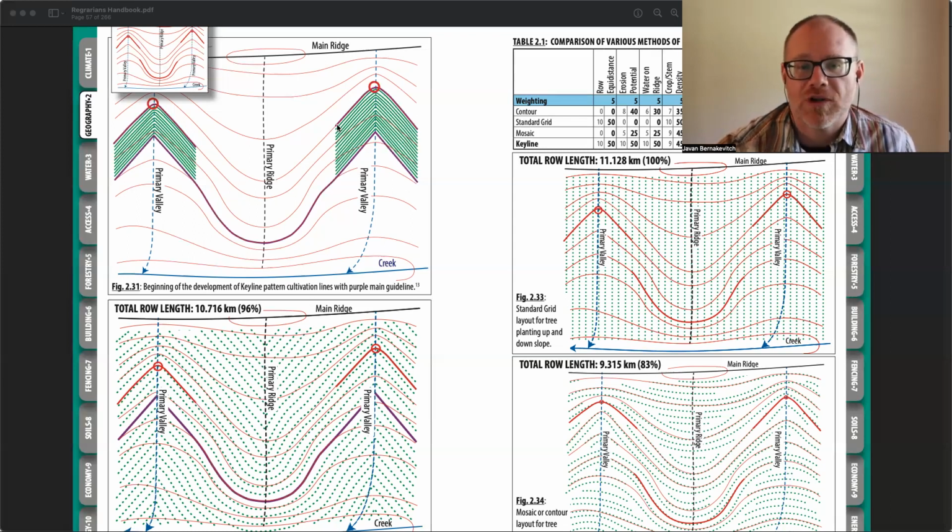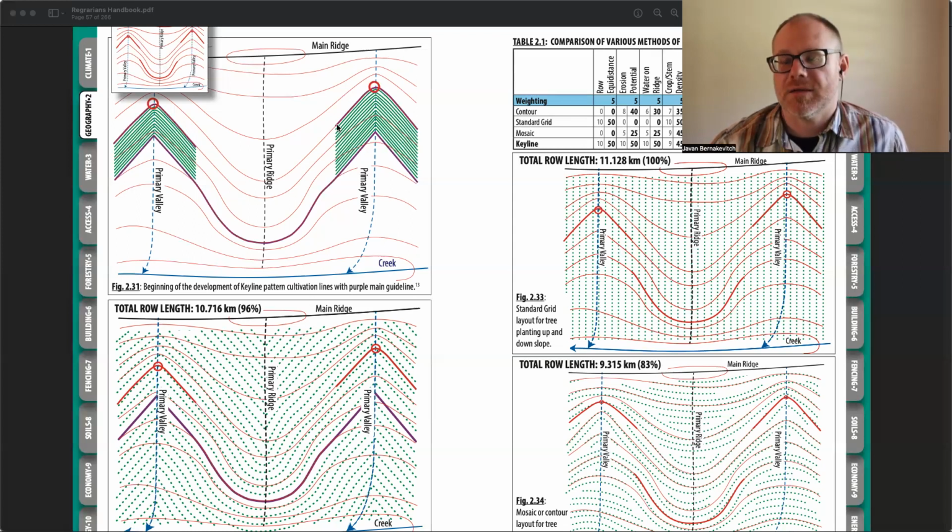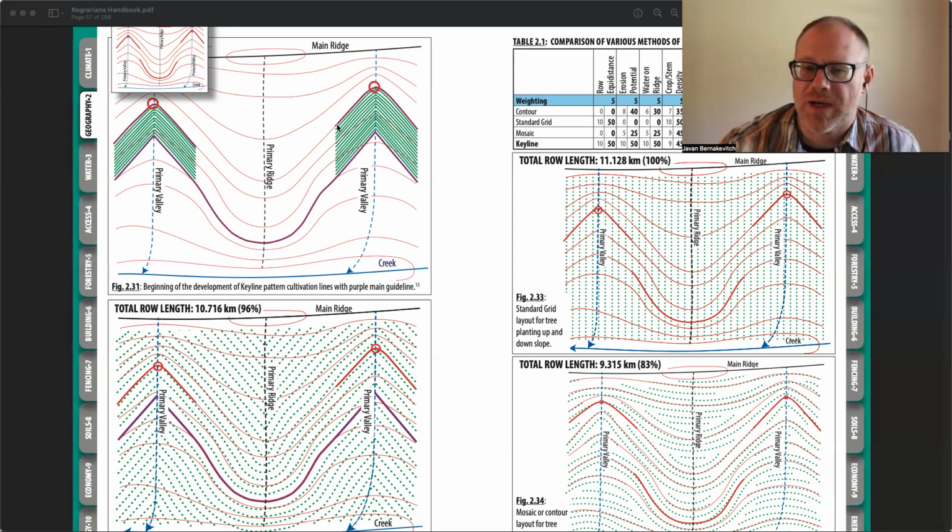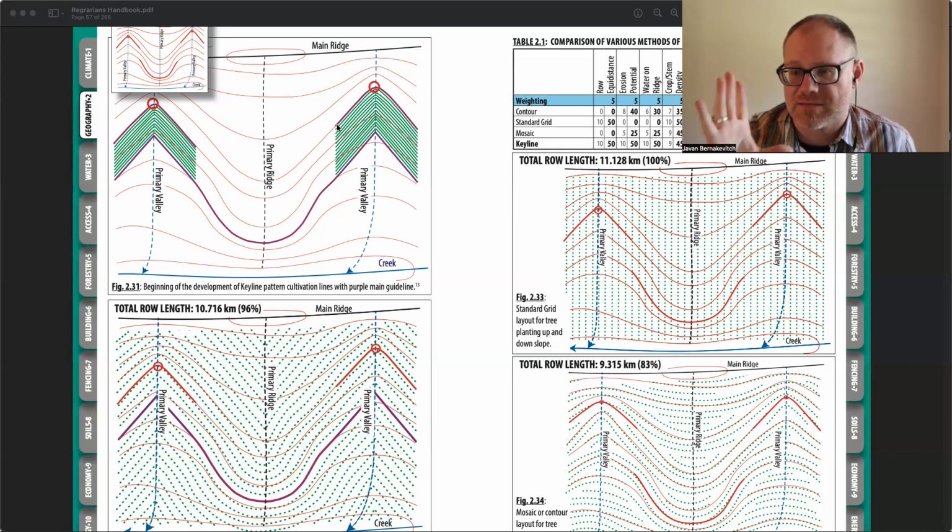And then once we have a sense of, okay, we've got 4 or 5 spots that we think are good, then we'll bring in a machine and do an exploratory excavation hole to see what kind of soil we're working with. Do we indeed have the clay to line this pond, or potentially create a keyway for our keyline dam? And a keyway is basically a way to put your wall material into a substrata of clay, so that way it's locked in.